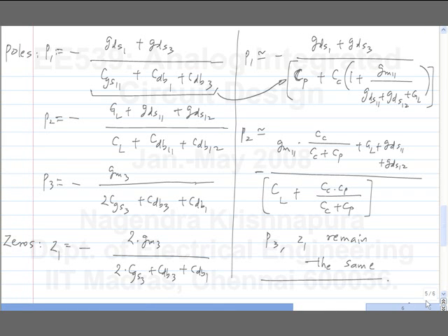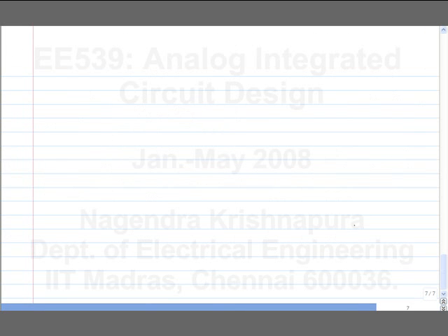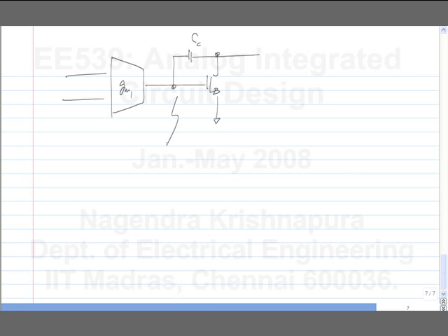So this amplifier is like this, okay? Now the second stage is also an amplifier. What is the incremental swing at this point? The output swing, approximately, is the output swing divided by the second stage gain. So if we assume that to be rather small, if the second stage has a large enough gain, then this whole thing is an integrator.